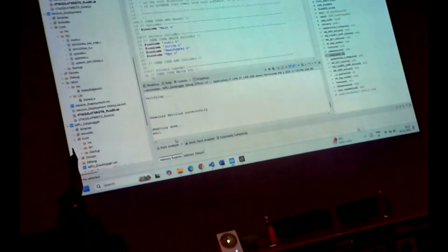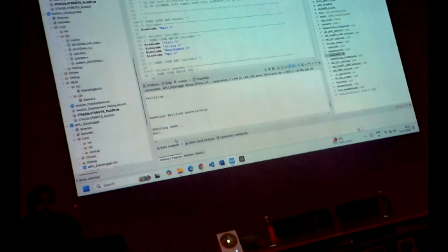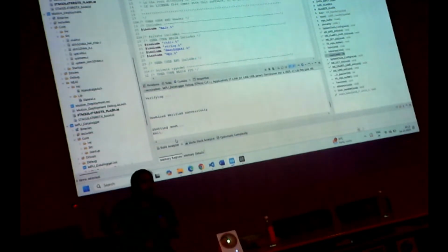Can everyone see this NEAI folder? Inside that NEAI folder, there is an inc folder and a lib folder. So these two, the Nano HAI header and the libneai.a file, we got from the machine learning model which we have built. In the Nano HAI NEAI folder, you just copy and paste these two files and give the path, so that your ML model is linked with this CubeIDE and you can write the deployment code and run it inside this microcontroller.